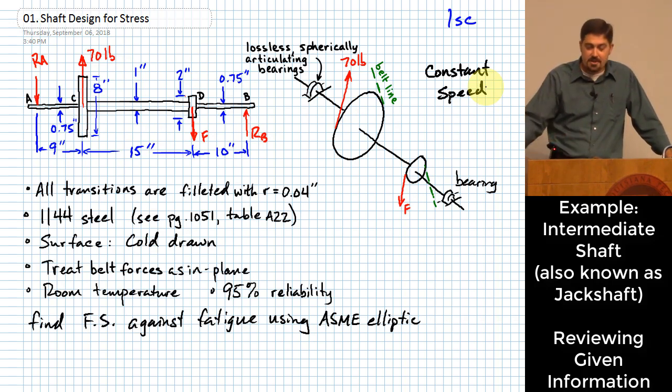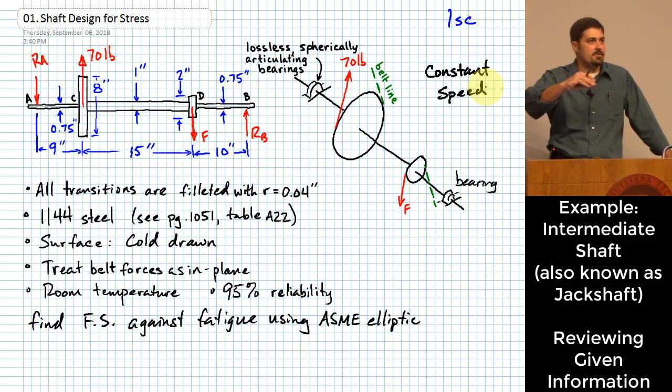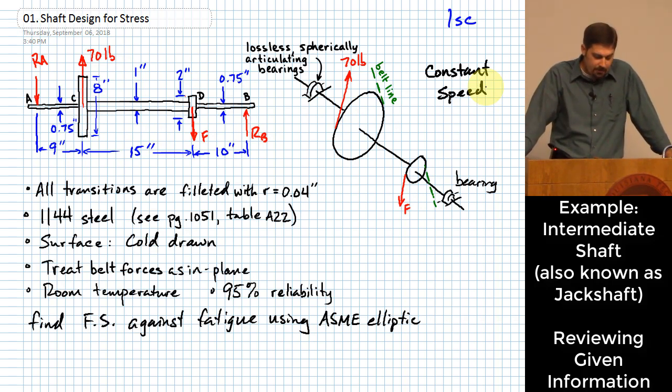Well, there's a stress concentration generated actually either way, no matter how you do it. But the larger you make that fillet, the more you mitigate that particular effect, right? You decrease that effect of having a stress concentration the larger you make that fillet, okay? If you have a perfectly sharp corner right there, then in theory, what that does is it creates an infinite stress concentration. In practice, it doesn't turn out that it's necessarily actually infinite, because generally in practice, infinite doesn't happen. But in theory, that's the direction it goes whenever that radius value gets really small.